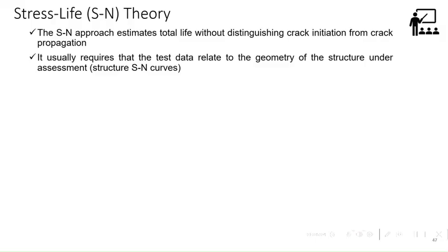We will come to know. I will tell you in the middle of that justification why it is preferable to have an SN curve for the particular component. Because when you are predicting a component's fatigue life, referring to an SN curve, your SN curve is a material SN curve, not the component's.